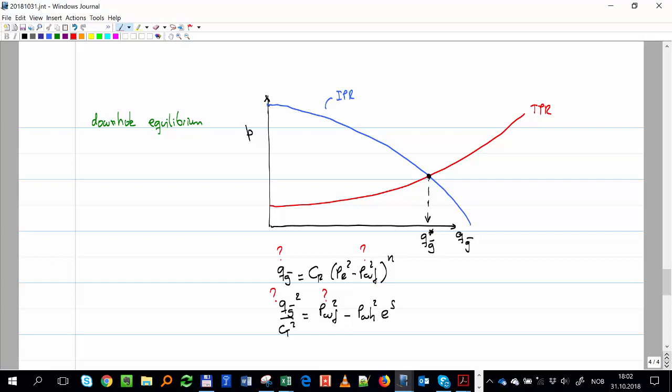Okay. The truth is, we usually don't have an analytical equation. For IPR, yes, but for the rest of the system, no. You don't have just a very nice, beautiful expression like that. You have to perform a stepwise calculation. So for those cases, it's better to use a solver. You create another function, which is the difference between those two, and then you drive it to zero, and that will be the solution.